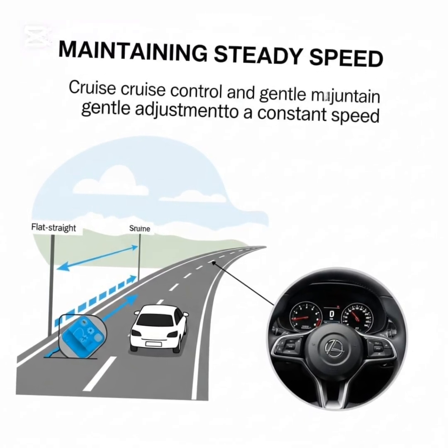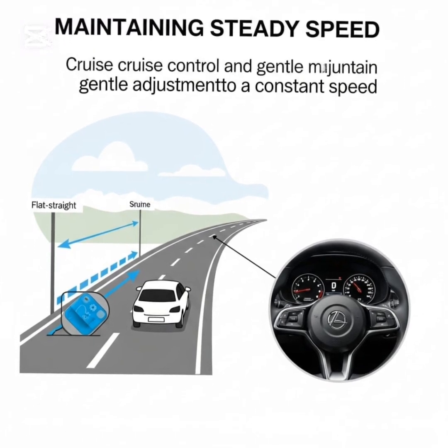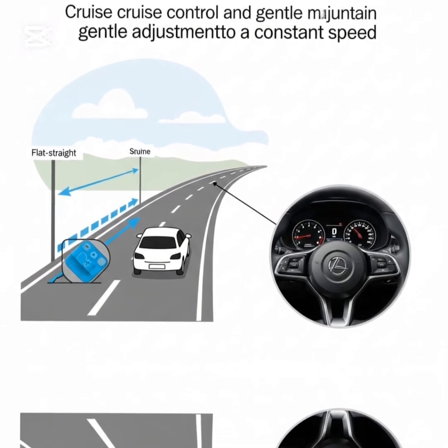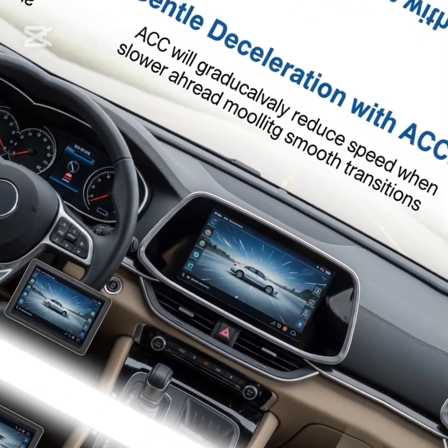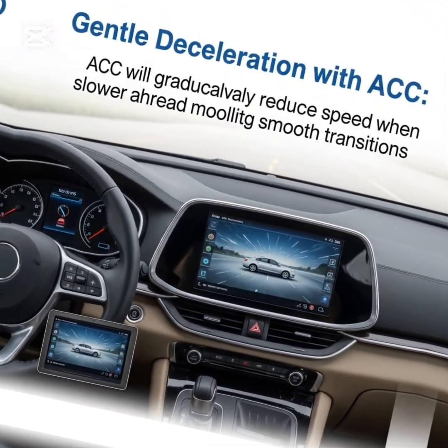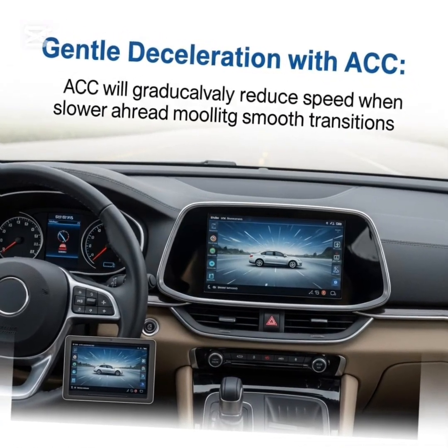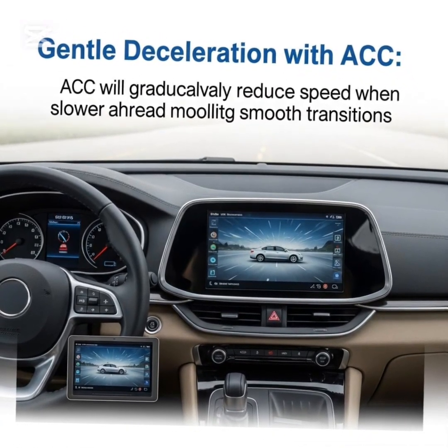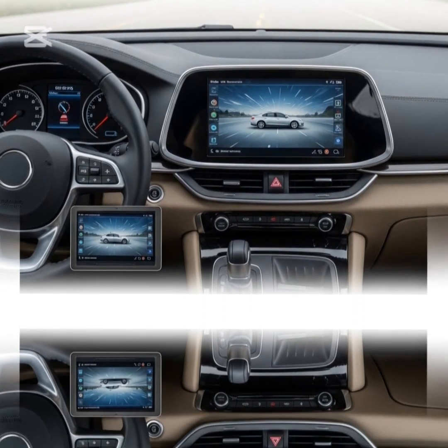Key highway speed control techniques include smooth acceleration to cruising speed, maintaining steady throttle position, avoiding unnecessary lane changes, using cruise control when appropriate. Sudden acceleration or braking at high speed can destabilize the vehicle. Gentle corrections are safer and more efficient. Maintaining proper speed also improves fuel economy and reduces driver fatigue.